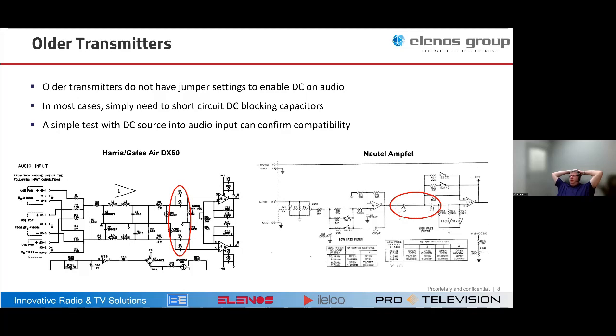So I think really, while maybe there's a tube rig that could be made to work, that's a little bit more of a science fair project. But a 35-year-old solid state transmitter's a pretty good candidate. Just an aside, the Continental shortwave rigs, I believe, have this built in, because their digital step modulator actually plate modulates the final, but it's a digital modulator.